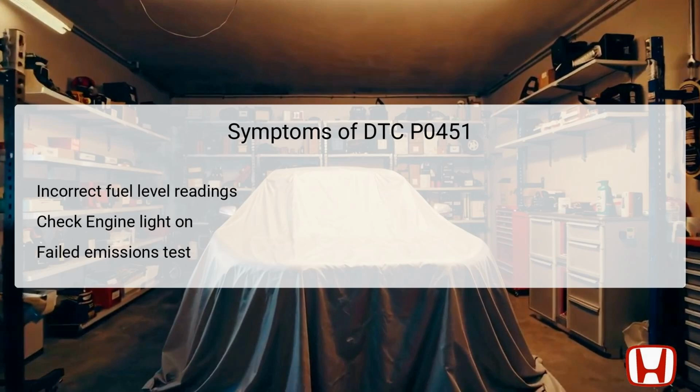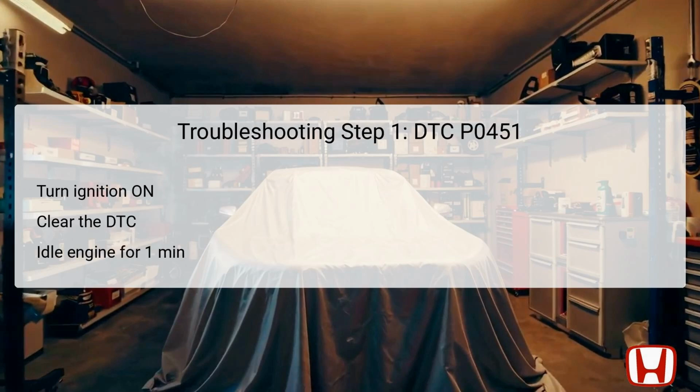It is important for vehicle owners to recognize these symptoms early to prevent further complications and to address the FTP sensor issues promptly. The first step in troubleshooting DTC P0451 involves preparing the vehicle's diagnostic system. Begin by turning the ignition switch to the on position, which powers the necessary components for diagnostic testing. Utilizing the Honda Diagnostic System, HDS, clear any existing DTCs. This allows a fresh start to monitor the FTP sensor's performance accurately.